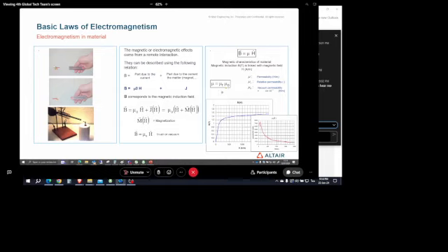So as you can understand, if you are in the air, the permeability mu is equal to the vacuum permeability. Aluminum, for instance, or copper, has the mu r equal to 1. So from a magnetic point of view, aluminum or copper behave as air or vacuum. That's why we are not using aluminum or copper as stator lamination or rotor lamination, because it will behave as air or vacuum, and we are not going to canalize the magnetic field.